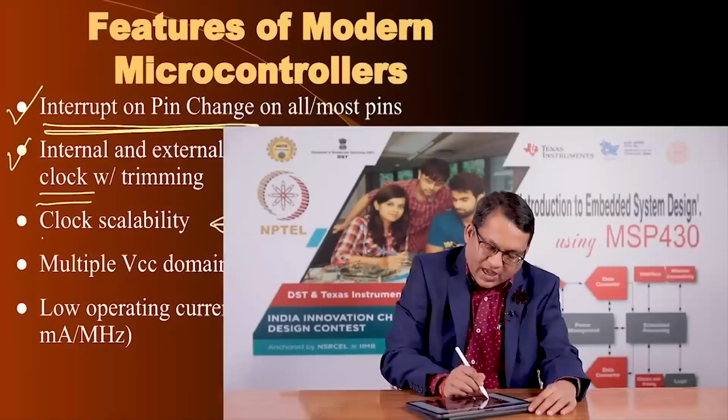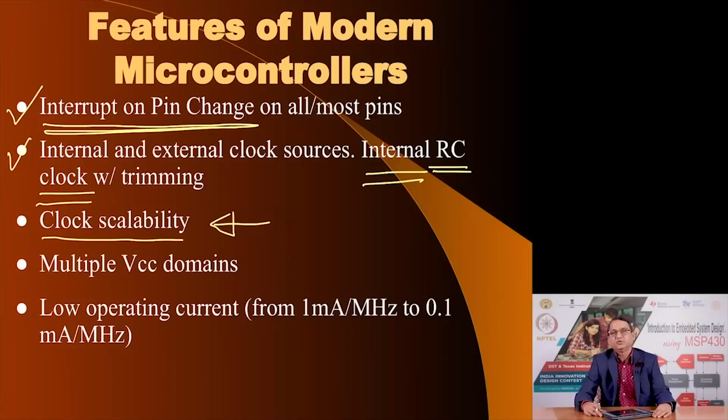And so you, as a designer, when you are looking for various features, you should read the data sheet of that microcontroller to find out whether clock scalability is an option or not. Also, modern microcontrollers operate at great high frequencies, in which case the power dissipation may increase, and to control that, oftentimes the chip is partitioned in multiple voltage domains, and therefore you would find that your microcontroller requires 2 or 3 different supply voltages. We will come to that feature when we talk about the ecosystem of a microcontroller.